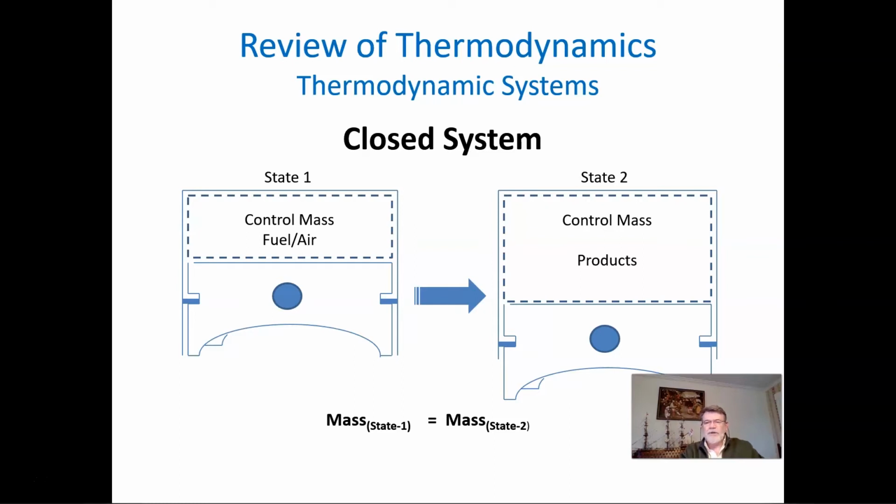So again, remember, a closed system means you basically have a defined space for your process or your set of processes, like a bubble around them. So this cycle here has a controlled mass for the system you have defined. So really, for a closed system, what is important is whatever you define as your system, the mass when you go from state 1 to state 2 should be the same, right?